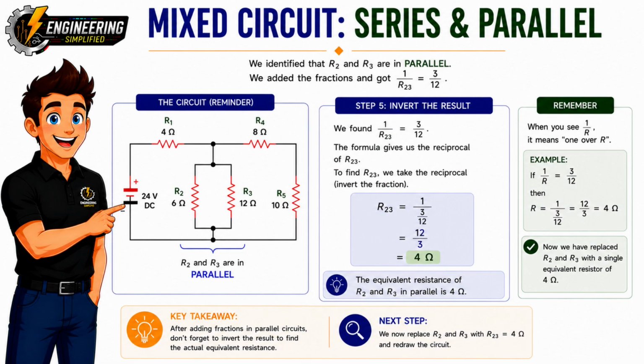We've almost finished finding the equivalent resistance of the parallel branch. In the previous step, we found that 1 over R23 equals 3 over 12. But remember, this isn't the value of R23 itself. It's the reciprocal, or 1 over R23. To find the actual resistance, we simply invert the fraction. That means we flip the numerator and the denominator. So instead of 3 over 12, we get 12 over 3. 12 divided by 3 equals 4 ohms. So our equivalent resistance is R23 equals 4 ohms.